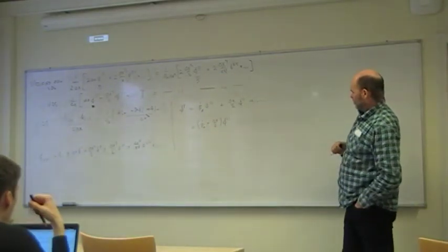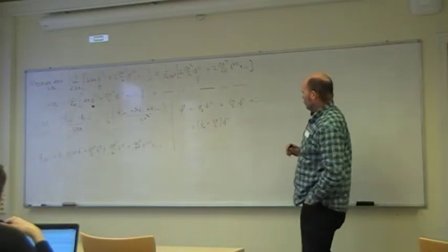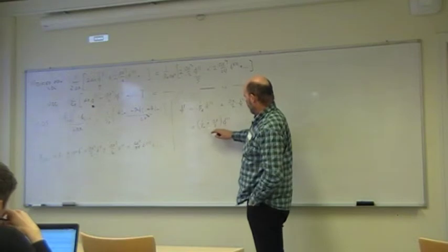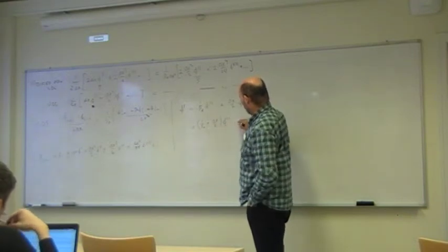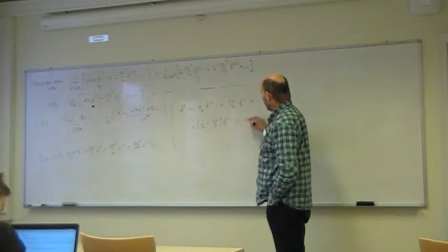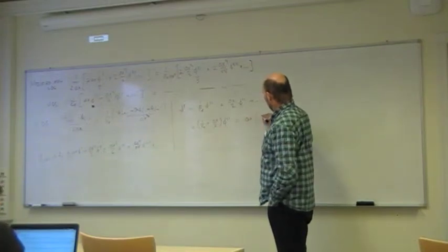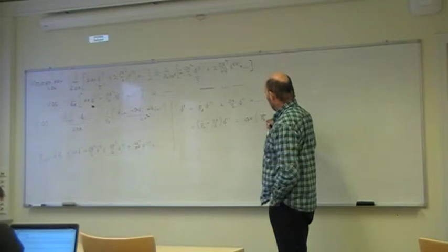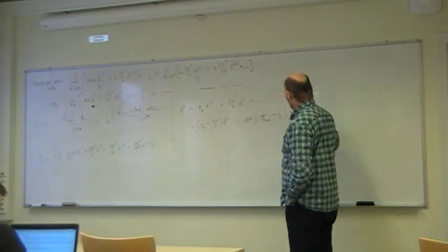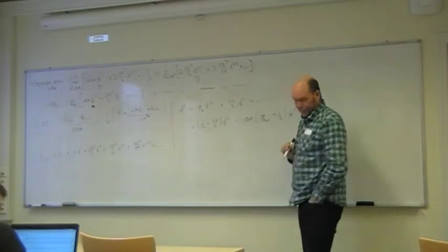So how should we rewrite that one? Let us multiply with 1 over delta x here. So then you can write it like delta x outside. Then you will have 1 over the Péclet number based on delta x plus 1/2 phi double prime.